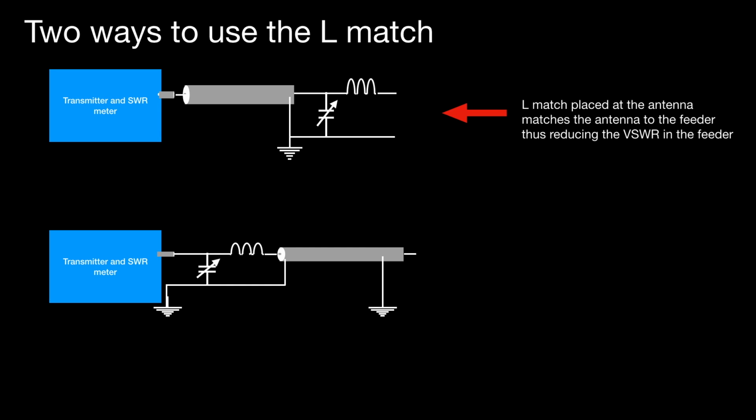The difficulty is, of course, that if your antenna is remote from your radio, which it usually is, it implies that you have to have an automatic tuner at the top of the mast or at the feed point, and this has to be controlled electrically by various devices to switch in and out the capacitance to make it operate. And you can see commercial versions of this, one made by ICOM, for example. Similarly, on things like yachts, they tend to have a masthead antenna tuning unit.